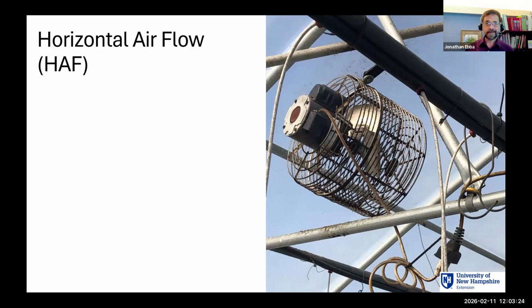One important thing is that this is not about cooling, right? This is about what I was just talking about. This is about that even distribution. So if someone says, oh, it's so hot in there, and I added a couple more fans, and what they mean is they put in more internal fans to move the air around, that's not necessarily going to reduce the temperature, right? Just because we sit in front of a fan and we feel cooler, I don't have time to explain why right now, but we feel cooler in front of a fan.